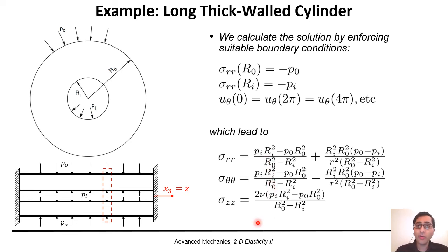Okay. You may remember that we could solve the same problem from Laplace's law by just assuming that imaginary cross-section. Let's see the difference between this more accurate approach and that more simplified approach by actually plotting the values for the stresses.